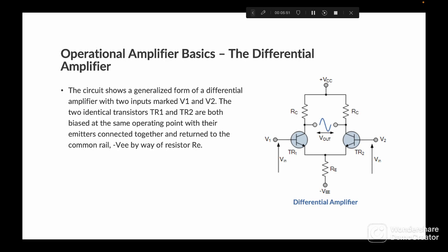Operational amplifiers on their own have a very high open loop DC gain, and by applying some form of negative feedback, we can produce an operational amplifier circuit that has a very precise gain characteristic that is dependent only on the feedback used. Note that the term open loop means that there are no feedback components used around the amplifier, so the feedback path or loop is open. An operational amplifier only responds to the difference between the voltage on its two input terminals, known commonly as the differential input voltage, and not to their common potential. Then, if the same voltage potential is applied to both terminals, the resultant output will be zero. An operational amplifier's gain is commonly known as the open loop differential gain and is given the symbol AO.